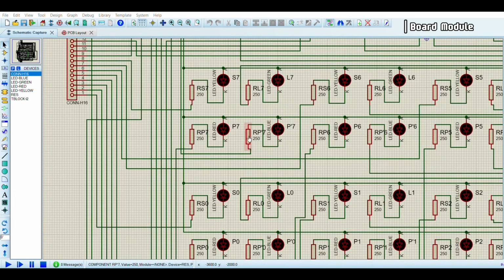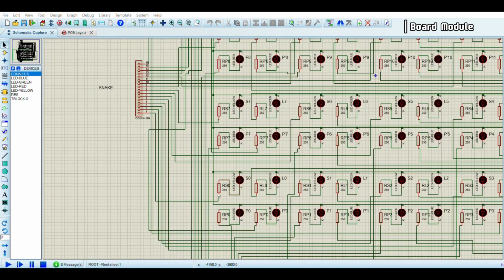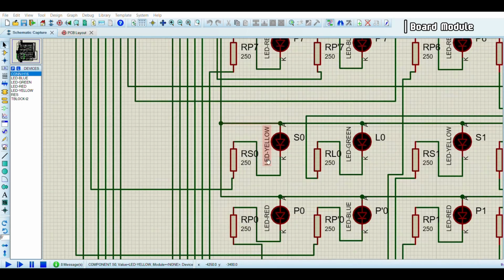And another thing, how do you calculate the resistance value? We calculated it in the tech shop video. We saw the LED's voltage rating and the maximum current rating. The LED's voltage rating may be 1.9 volts. So we took the maximum current also, 10 milliamperes.